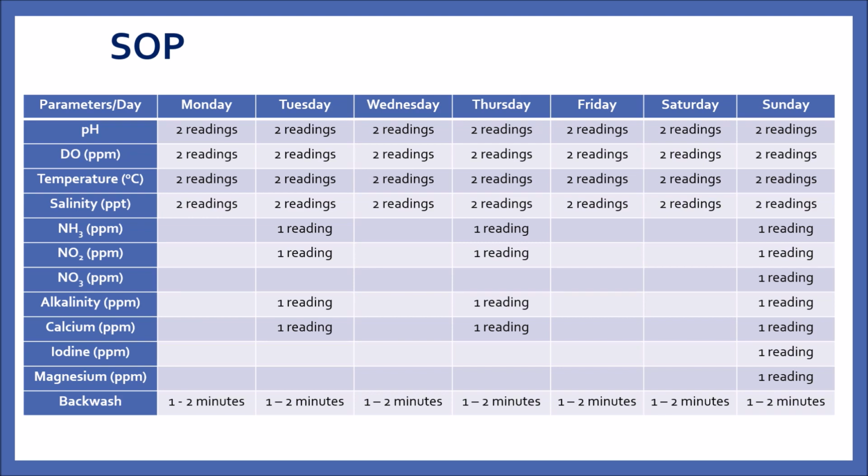Alkalinity, we are utilizing a titration kit. We can take it every other day, as well as calcium. Magnesium and iodine are not key values and you can take them every week. For the SAM filter, we're recommending backwashing every day for 1 to 2 minutes.